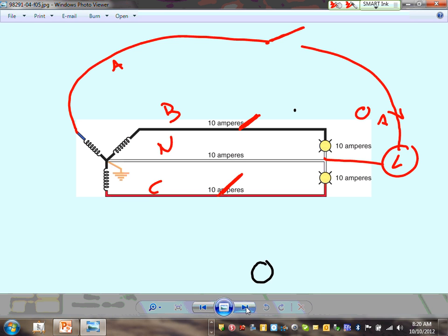But here's my argument. I hear you. Actually, engineers specify a neutral because of harmonics on certain loads. We specify a neutral with every circuit. But take this: if it's not specified as a multi-wire branch circuit, no question asked. Now here's my question: how often do you really have a ground fault in a lighting circuit? Well, I think it's more of a maintenance issue. If you turn off the circuit, you don't want to have to turn off all of them if you have to work on them. Yeah, I can agree. Now, having said that, what happened in 2008 when the NEC code book came with disconnect switches for double-ended fluorescent lamps?